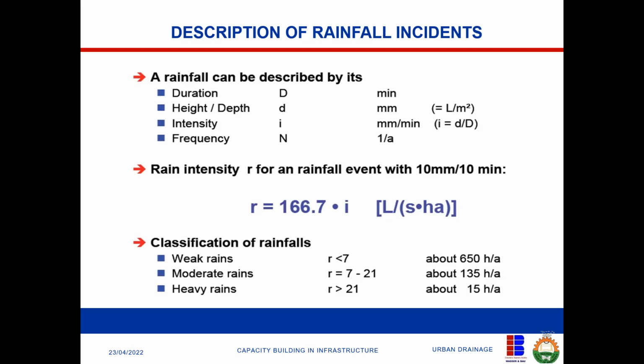And this is very important. As engineers, as designers who do design, you must use the worst case scenario, the highest expected. In storm events, we talk about probable maximum flood. You'll be hearing about it. If you're doing your design, you're not interested in all those small floods that come in June, July, August. No. You're looking at that one that comes once in a while and causes problems. I will explain again.